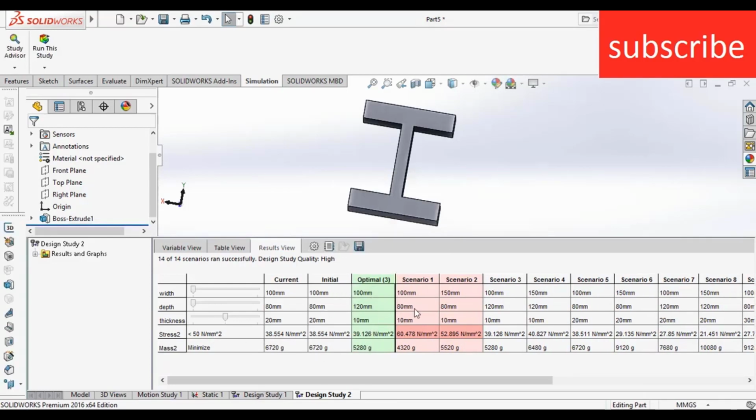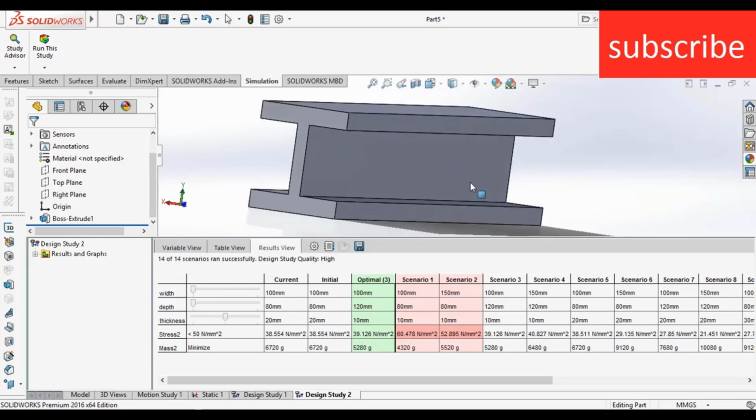Here my simulation is done, and you can see when my width is 100 mm, depth is 120 mm and thickness is 10 mm, at that point I got a stress value of 39.126 and a weight of 5280 gram. And here are the current values. At current, my width is 100 mm, depth is 80 mm and thickness is 20 mm. What you can see is it increased my depth and decreased my thickness. Because of that, I got this value. So this is how optimization works.